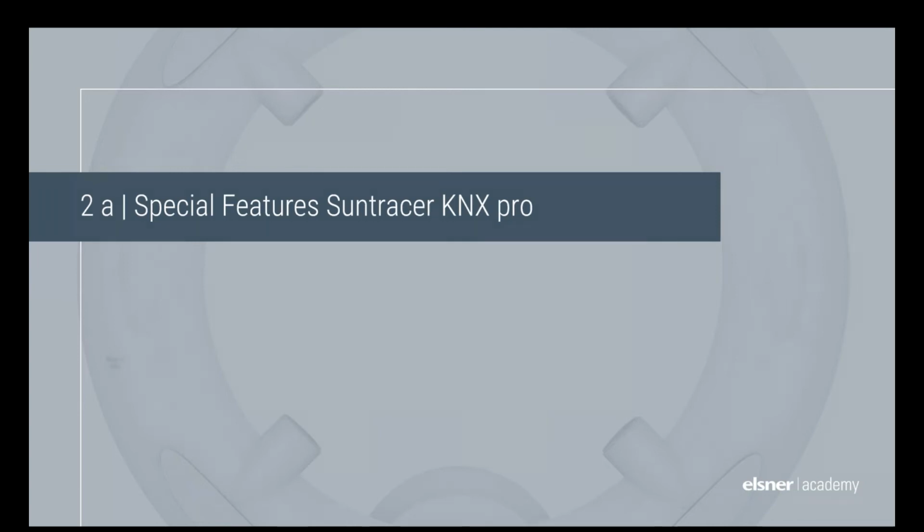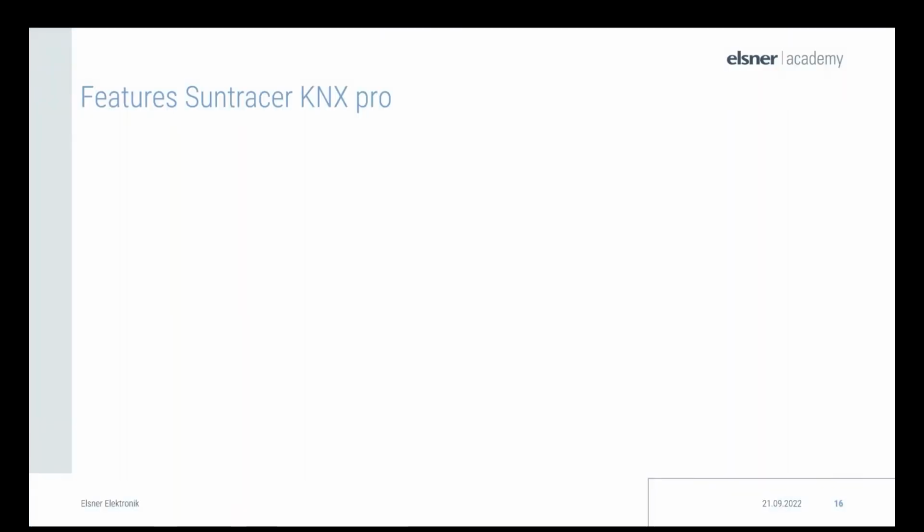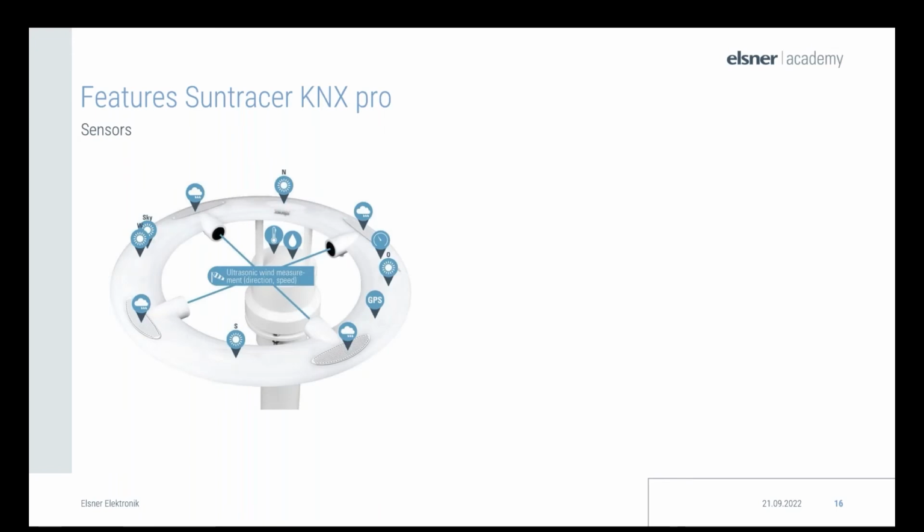Let's continue. Okay, so first of all, let's check out the sensors that the Suntracer KNX Pro has. Here you can see a little graphic and a visualization, but let's go into that in more detail. First of all, of course, we have the temperature measurement, which is a very important value that you should always send to your KNX bus so you know how warm or how cold it is outside. This is important for realizing, for example, automated heating or venting functionalities.